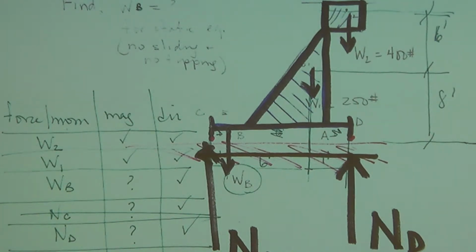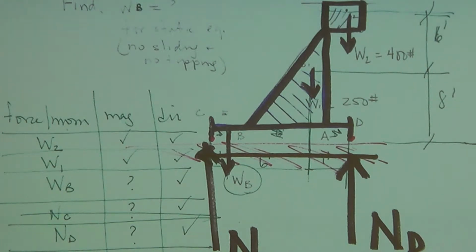So let's say we put friction in there. What would we find out? If we were analyzing it the way I said, if it's tilting like this and what's holding it is more rough on the bottom, and we put a frictional force like this, how would we determine our value for the frictional force? Do an equilibrium equation. You have 2 more unknowns, right? You guys, it's easier than you think, you're making it more complicated. Look at all the forces on there. What equilibrium, yeah, Kyle? Sum of the forces in the x equals 0, and what does the friction equal? 0. Then you just determine that friction isn't the problem.